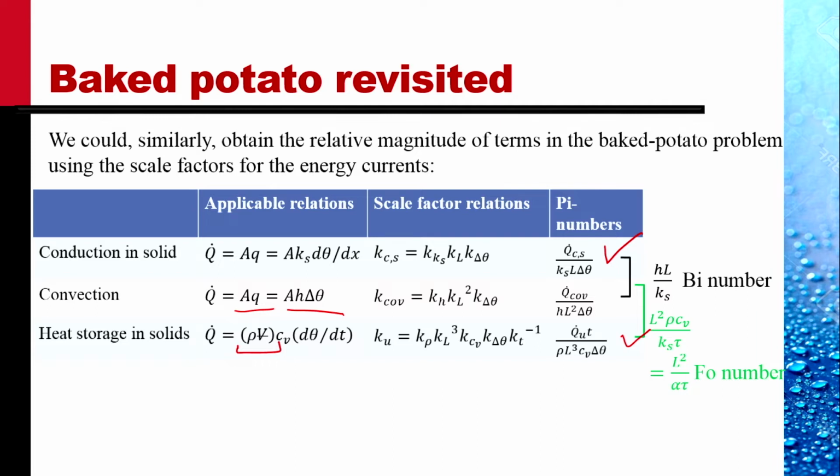So thus we see in both these examples, we obtain the same ratios of the forces or the same ratios of the fluxes as we obtained from the original governing equations and boundary conditions. There is no need to start from those equations. We could start from these considerations of scale factor relations.